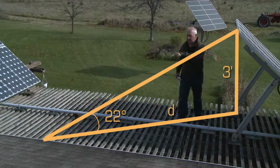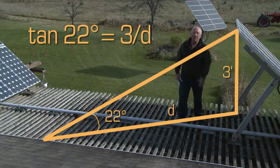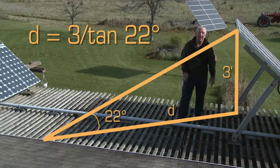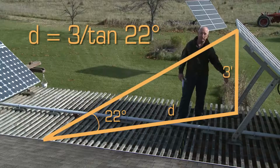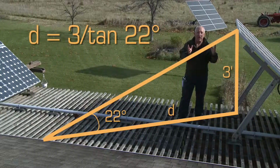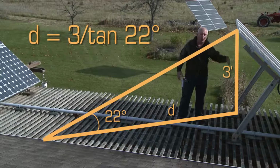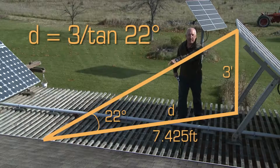So I have the tangent of 22 equals 3 divided by D. Shuffling the equation, I can solve for D, and I see that D, this unknown, equals 3 divided by the tangent of 22 degrees. I don't have a calculator in my brain, but if we calculate that out using the numbers from our 30-degree latitude sun chart, and we use the 3 feet, I think we end up with something over 7 feet for this distance right here.